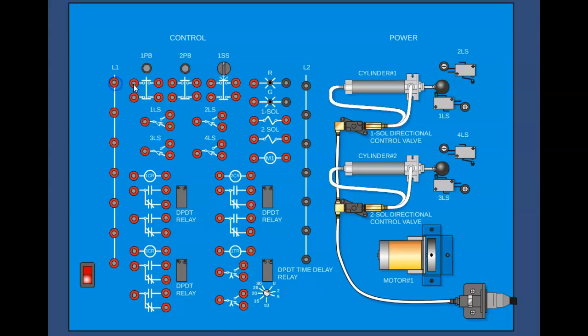So I want to first wire up and look at the normally open relay contact. It's the one that gets used most often. So I'm going to do what we normally do. We would start with our power side, go through a switch, and come out of our switch, and we'd energize a relay coil. And so we're getting power to the coil, and we've got to take the other side to L2, which in this case is our ground for DC. I wanted that to be black, so let me kill that and change that to be black. There we go.